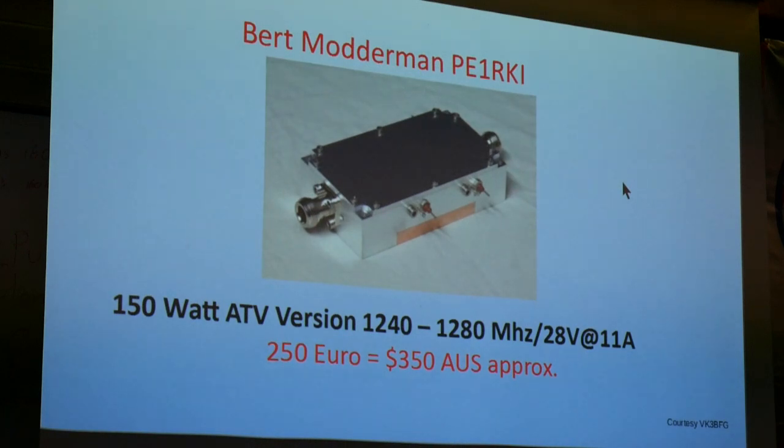Because this is where you need a spectrum analyzer. So when you're putting your signals through these, you know that nice square-shaped signal, well, it doesn't stay like that for too long. If you start pushing it up, you start getting replicas of the spectrum coming up at the sides, so you'll start to see, you know, it's coming up here. But 40 dB down is nice. 30 dB, yeah, that's probably pushing it, but that's what most people end up with, because I've got to try and get a signal out somehow.